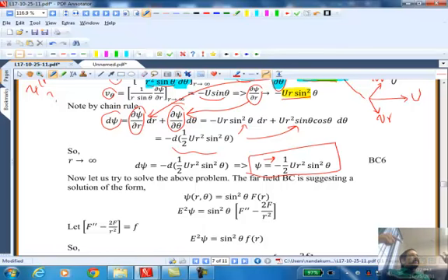So we have converted all the boundary conditions in terms of the stream function. The stream function close to the boundary is psi is 0, d psi dr is 0. The boundary condition far away is psi approaches this functional form. Okay, it is still a function of r and theta far away, but it varies as r squared as r goes to infinity, and it varies as sine squared theta. It is this function that's going to give us a clue on how to construct the solution to the differential equation. Again, this is just simply given in Bird, Stewart and Lightfoot.